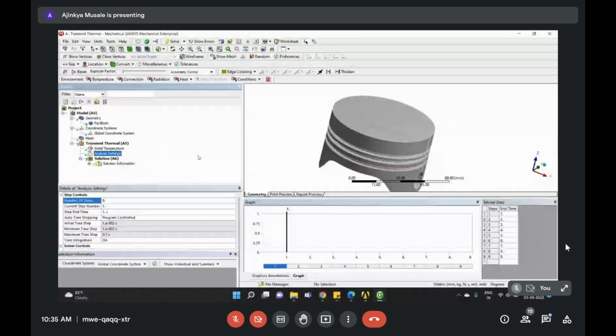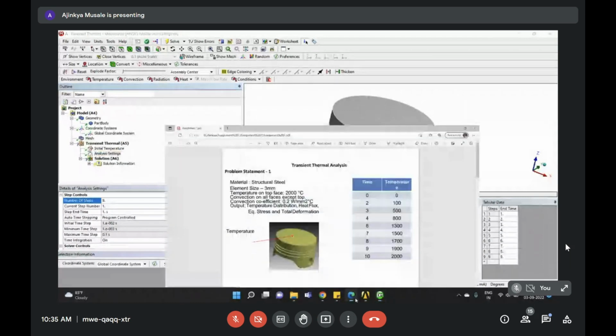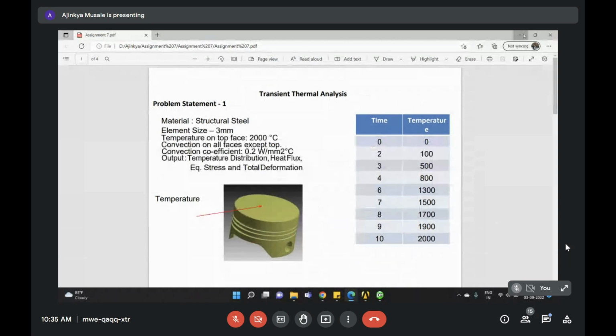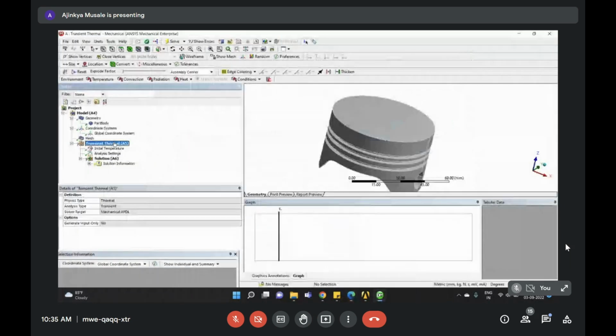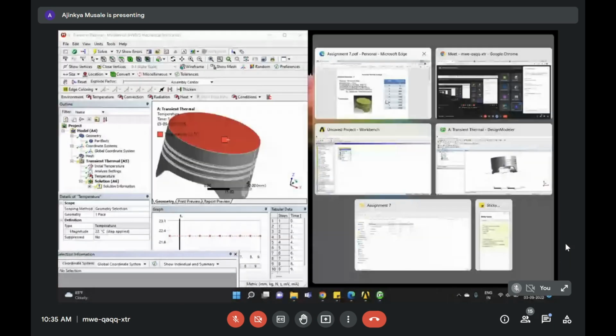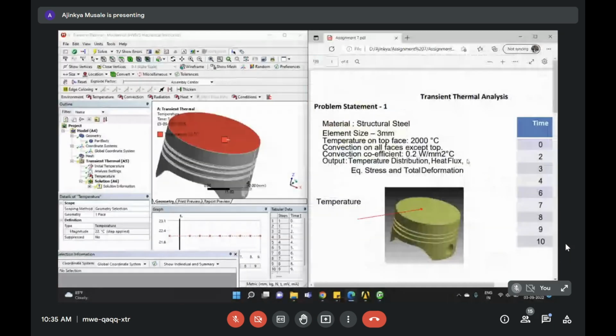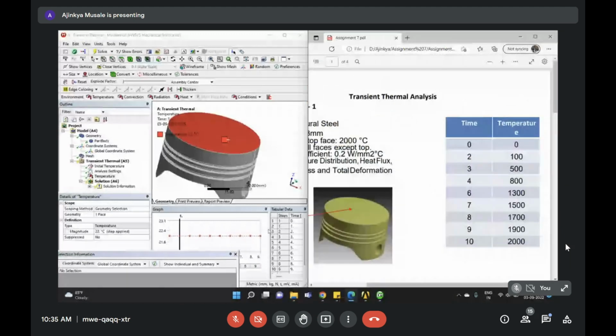Now we'll simply move to the boundary conditions. Let's see what boundary conditions we have. First is the temperature. I'll click on thermodynamics inside and say temperature. Where? On the top face. Now maybe I will drag it so we can see it side by side. Then it will be easier for us to type. Okay, I guess it's visible to everybody.